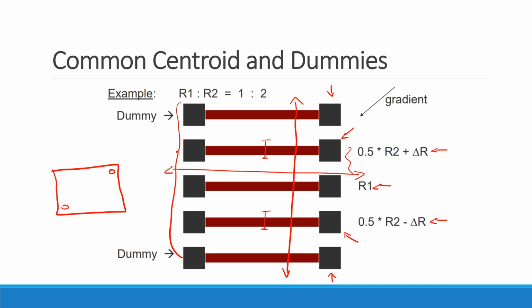So the dominant effect tends to be the etch effect. But by the way, just to make sure these, let's say, 32 or 45 nanometer processes work, people are coming up with all kinds of funky stuff. One example is that people are now actually mechanically straining the transistors. They put these capping layers that literally are either stretching or compressing the channel. Well, guess what? It's a mechanical thing. So if there happens to be some other capping layer not that far away on one side, and no capping layer on the other side, you get a different stress. And therefore, you get different characteristics. So bottom line, if you care about it, just make it the same.